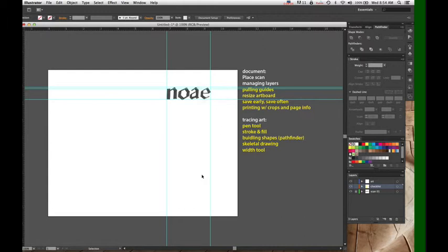So I'm just going to take it from the top. This white document that we are working on, this is the artboard. This gray background, this is the workspace. A good analogy is that the workspace is like the top of a physical desk, and the artboard is like the piece of paper on the desk. You can have all kinds of stuff on the desk that is not on the paper, and if you pick up that paper and carry it away, only what is on the paper will stay with the paper. It's the same way with an artboard and a workspace, and that's why I put my checklist out here in the workspace. Once I print this document or make a PDF, this checklist will not appear, because it's not on the artboard. It's just off in the workspace. It's off on the desk, not on the paper.